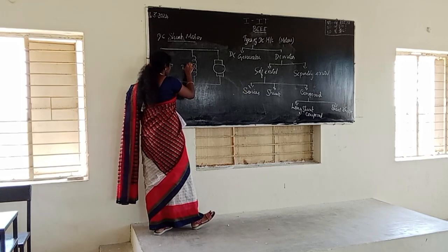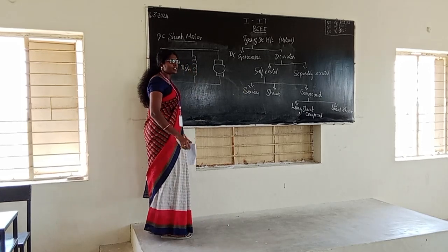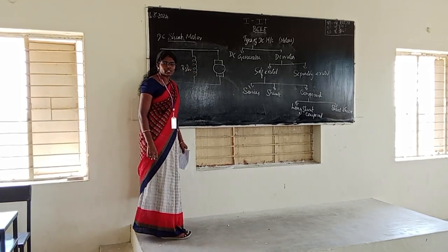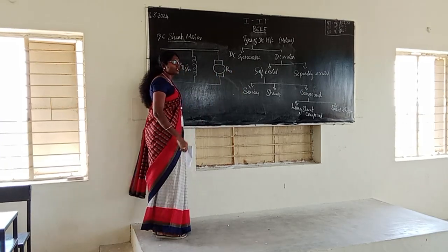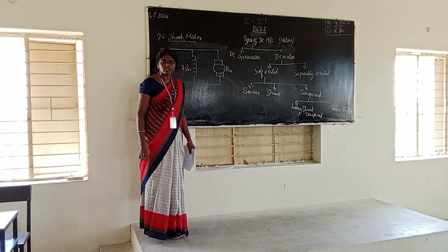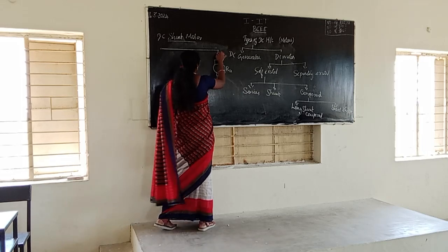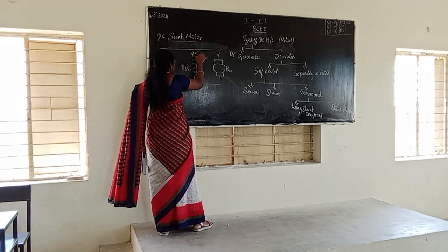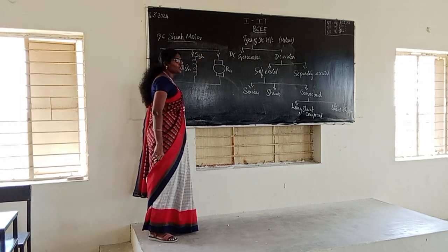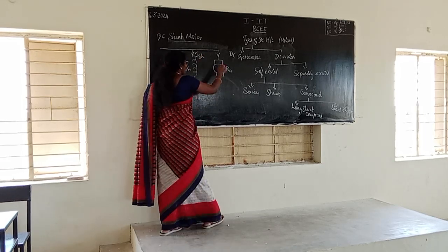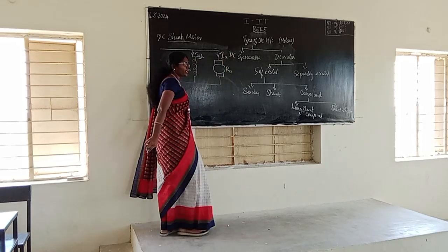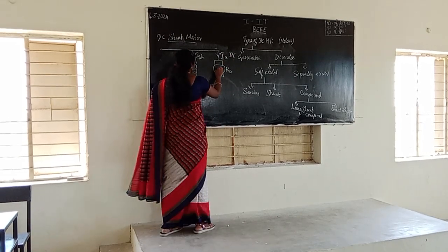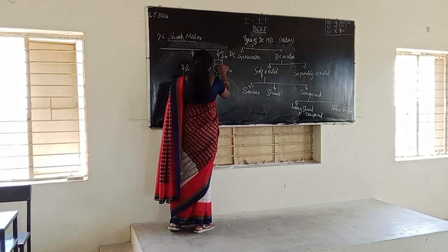So here is a resistance, and we will call it the resistance in shunt, or R suffix SH. In the armature there will be an inbuilt resistance, that is R suffix A, since it is the armature resistance. The current over here is I suffix S, the shunt current, and the current over here is the armature current, I suffix A. And now this is our motor.